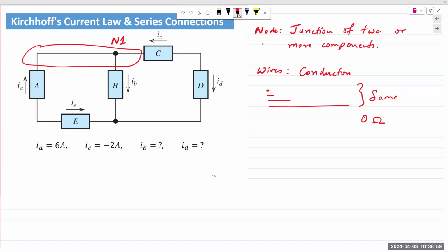Practically in real life, that extension cable will have some resistance. It'll be very, very small, a few ohms, but it'll still be there. It just does not rise to the level of interference. Make sense? A 100-foot extension cable will still give you the power outlet voltage at the other end. It doesn't matter that it's 100 feet long. Similarly, it doesn't matter how long these wires are, they are still the exact same node.